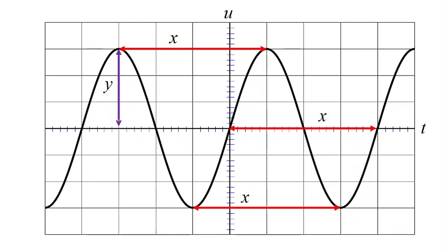Y represents the vertical number of divisions for a crest, for a peak. And SV is the vertical sensitivity, which is the scale, the voltage corresponding to one vertical division. For example, if SV equals 5 volts per division, each division vertically corresponds to 5 volts. In this case, Y equals 3 complete divisions, therefore the voltage will be 15 volts, SV times Y.